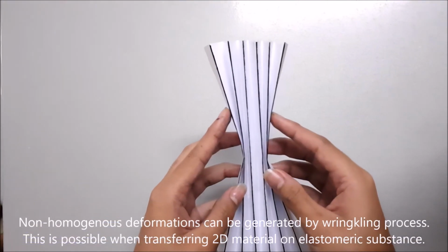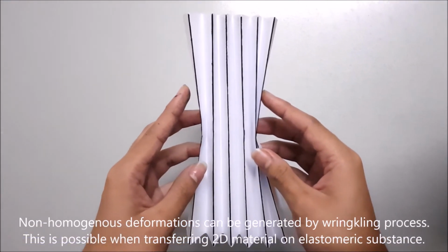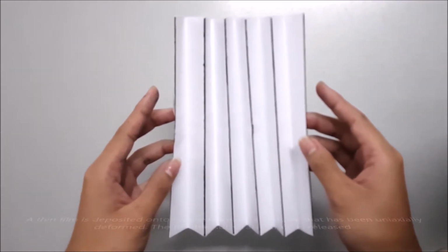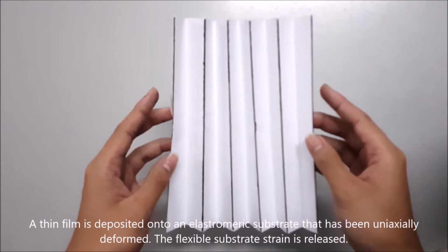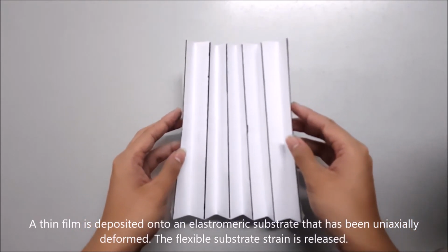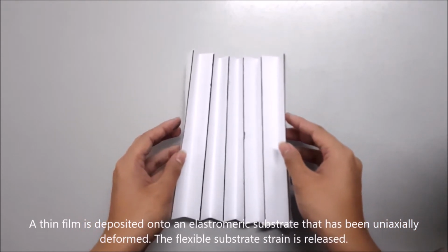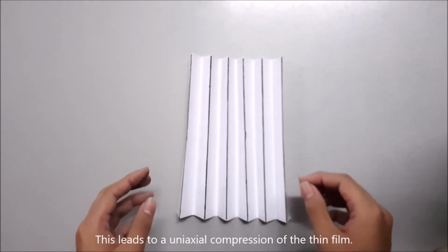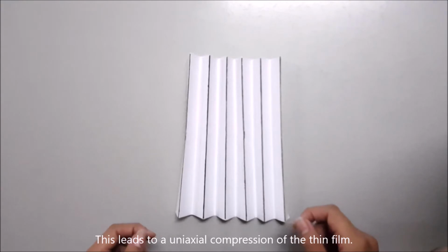Non-homogeneous deformations can be generated by the wrinkling process. This is possible when transferring 2D materials onto elastomeric substrates. A thin film is deposited onto an elastomeric substrate that has been uniaxially deformed. The flexible substrate strain is released. This leads to a uniaxial compression of the thin film.